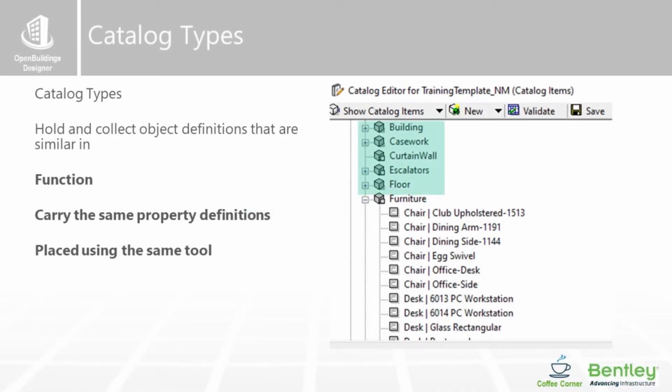So when we talk about the data group system, it's a property schema. It's a hierarchy of information where we define an object as a type. We then have properties that are relevant to that object type, and we can use those properties to report, to investigate the model, to generate quantities, etc. So there's a core concept I just want to refresh for everybody.